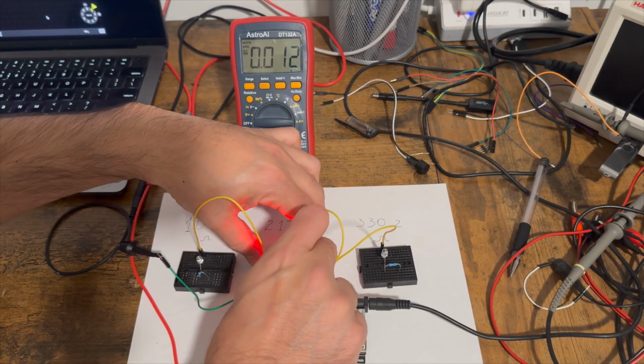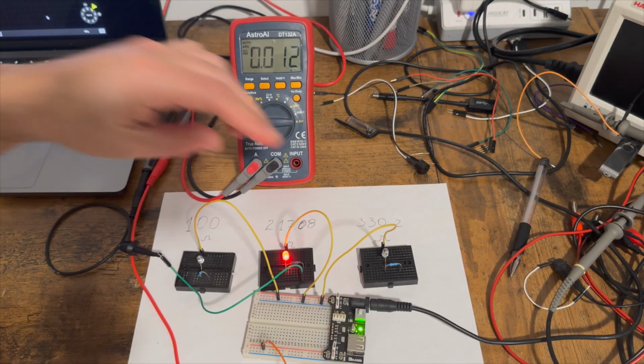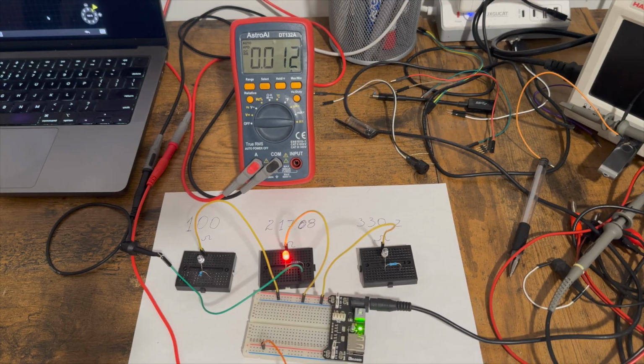We can see here that we are drawing 12 milliamps, and you can see that the LED is still bright, right? It's still shining very well. So 12 milliamps is very easy to be driven by a GPIO in a microcontroller, which usually sources 20 milliamps of current, but we should not push it to the top. We should have some gap in there in order for us to not stress our microcontroller. So this one would be a very good configuration to drive an LED using a microcontroller.